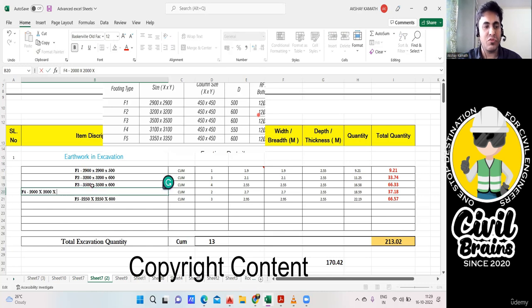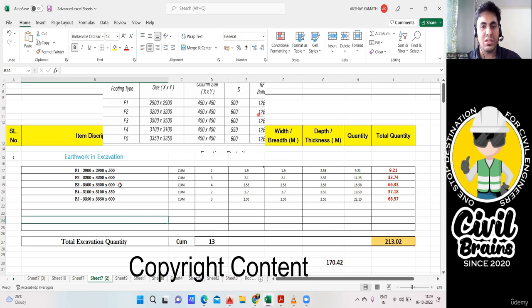Okay, next F4 footing. After this, I'll tell you one more trick where you can make even simpler Excel sheets, where you don't have to write all these names every time. I'll tell you after that. Let us finish this first. F4 is 3350 into 3350, multiplied by 600. Done. All the footings are written: 500, 600, 600, 550, 600. Just have to verify. Whenever you write something, try to cross verify it. Done. So this will be in cubic meters.